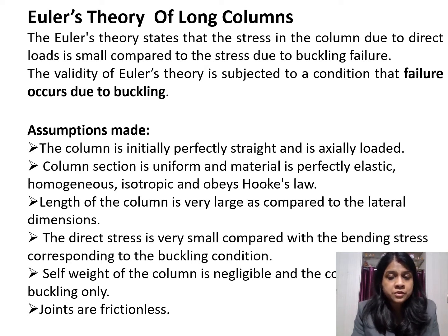As we have just discussed, in the case of a very long column, when compression load is applied to it, the column will start to buckle first. It will start bending instead of compressing. So he has made the assumption that the direct stress is very small compared with the bending stress corresponding to the buckling condition. The next assumption he has made is that the self weight of the column is negligible, because